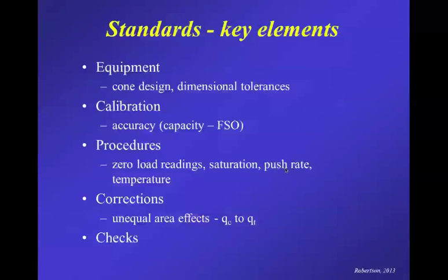And then there's push rates. The standard rate is 2 centimeters a second, but there is a little bit of flexibility. It doesn't have to be exactly 2 centimeters per second. In general, it's not that sensitive to rate. And then an issue about temperature, which we'll talk about. And then there are corrections, which we'll talk about, and checks and maintenance, which we'll discuss.